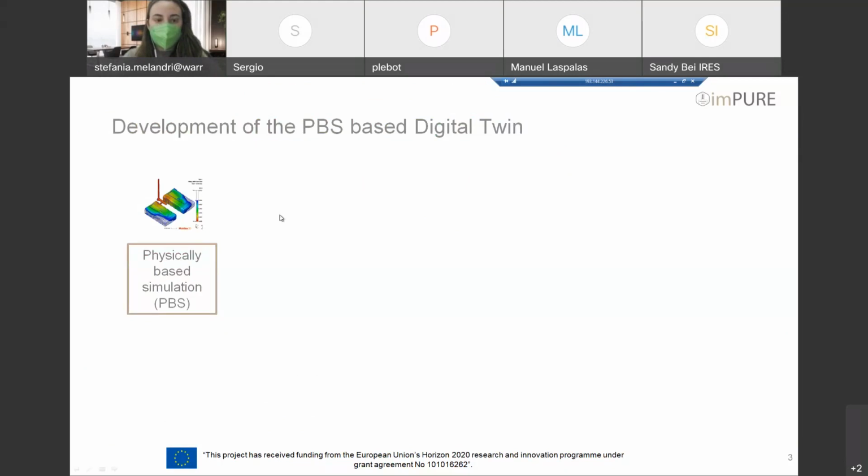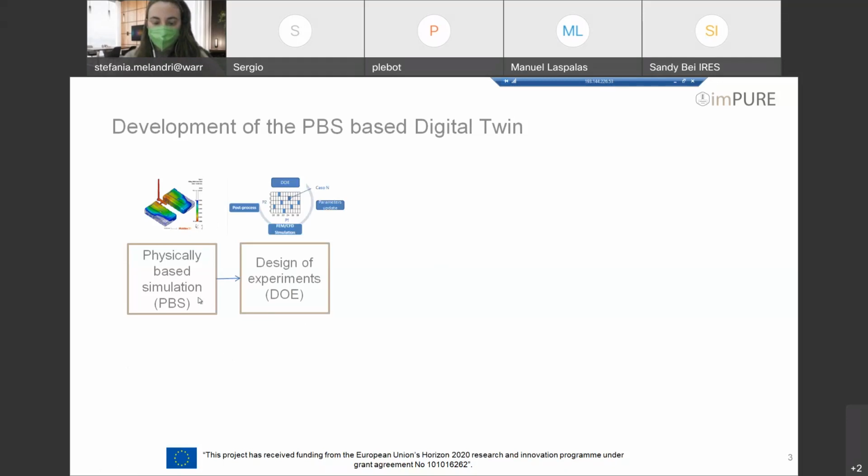So first thing is you need a simulation model that reproduces what is happening to the material in the transformation process during injection molding. Next, what we are going to do is exploit this model to analyze processing windows of all the input parameters that we have freedom to change in the machine.